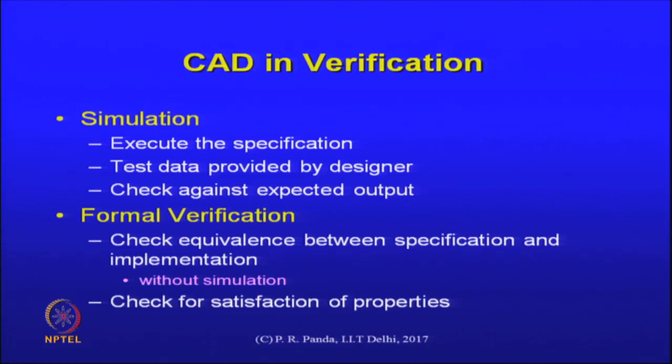Simulation is a common mechanism. Having designed it and having implemented the system, you execute the specification. The test data is provided by the designer or verification engineer, and you check the output of the simulation against an expected output of the system. So, that is simulation. This is a common mechanism, and normally chips that are designed, you always take through simulation, but often it is not sufficient.